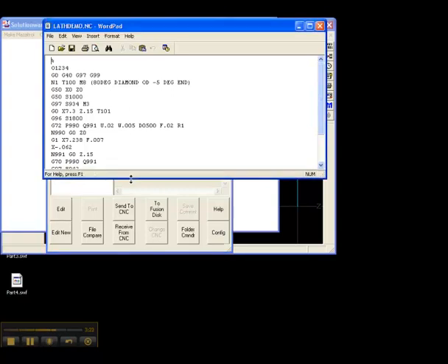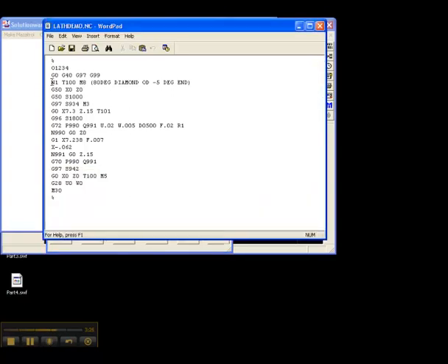Here's the G-code program. We only have one thing going on here. Here this is prepping tool 1. This is no offset. Here we have fixed RPMs, just to get the tool close apparently. And then here we're actually calling up tool 1. Here is the constant surface speed on once it gets close to the part. And then this is the canned face rough cycle, the G72. Going on down here, this is the canned finish pass. And then it puts the tool away, cancels the tool, and M30 calls it a day.